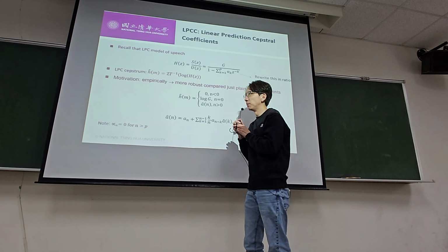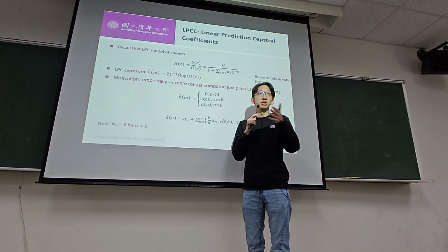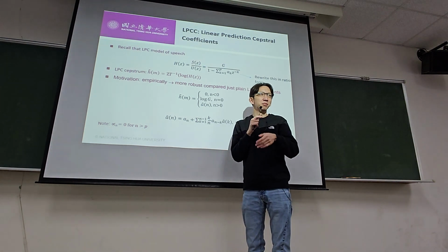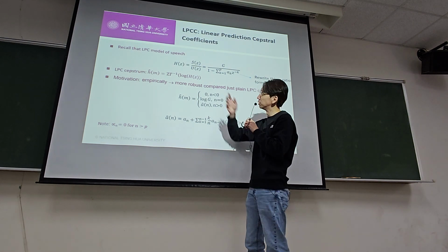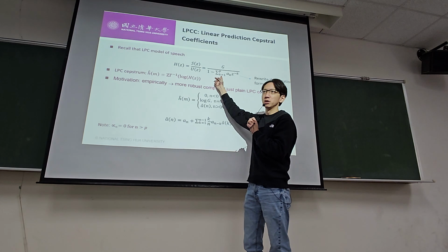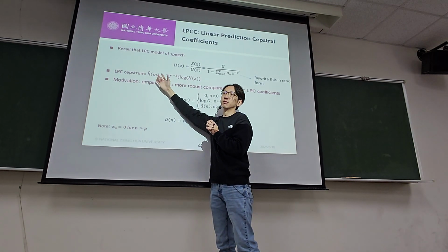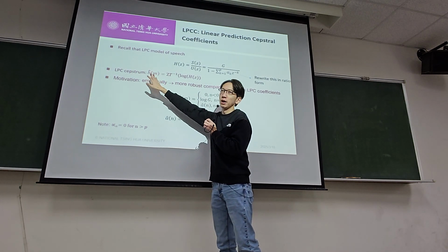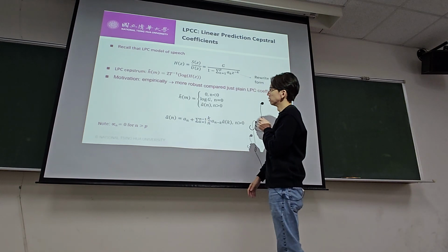The better way to think about this, from my introduction to signals and systems, is that they are all signals. We just talk about one of them as a system because that gives us a better mindset. So this is a system, and this is also a signal. If you want to take a transform on this signal, we get a Z transform, then the inverse Z, and take a log. That's your cepstrum analysis. So the cepstrum of the LPC is basically the inverse Z transform of the log of H of z.